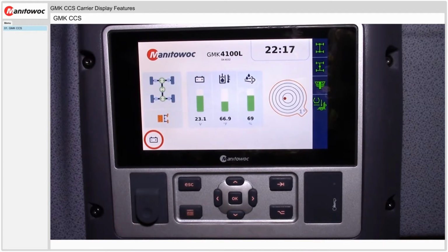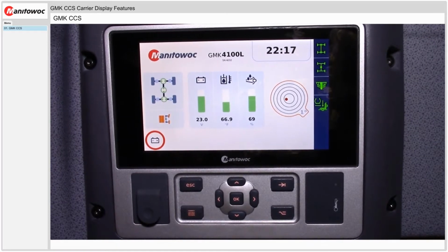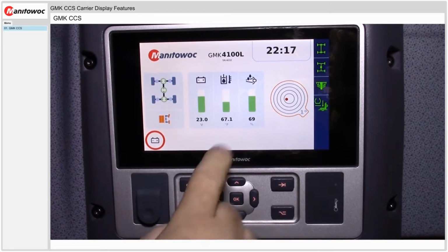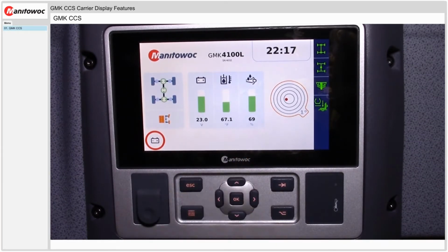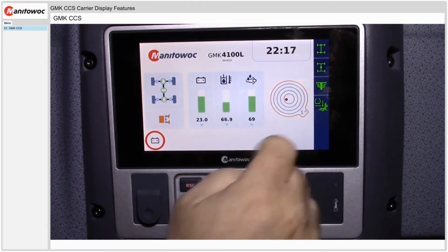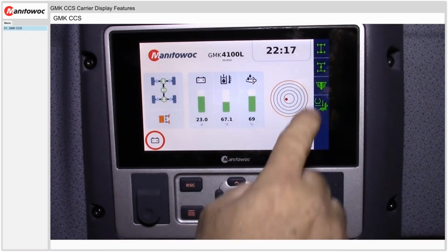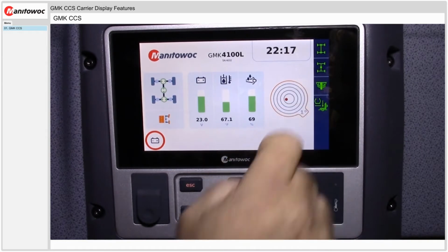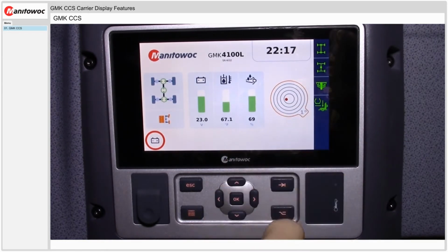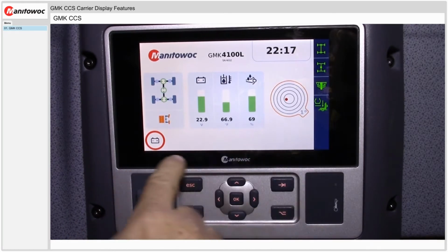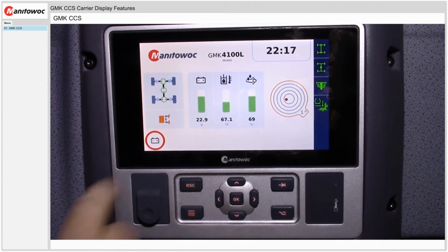With the crane ignition on, the startup screen is first displayed. On this display we see battery voltage, hydraulic oil temperature, and DEF level. Also we have indicators for the differential cross locks, longitudinal locks, suspension status, transfer case status, level indicator for the carrier, and steering status. Also we have warning symbols on the bottom. This warning symbol tells us we have low battery voltage.